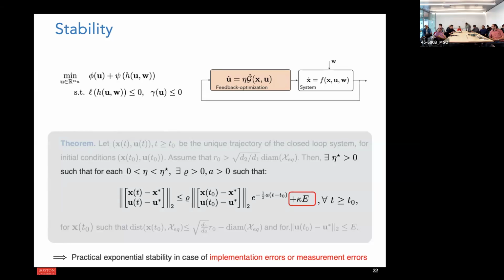Perfect. For things to actually work, when might this break? Yes, so the two necessary assumptions are that the two subsystems, when taken independently, are stable. Meaning that I take the plant, I fix the U and W, and it's going to be locally exponentially stable. And the same applies to my controller. But again, the key here is that, as explained in the 60s, when we stitch them together, you need to have sufficient timescale separation.